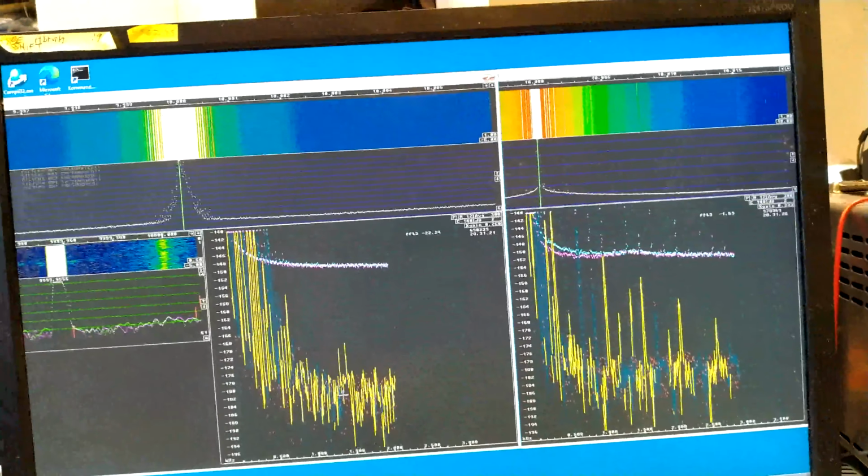And it's the same here. There are spurs, not very strong, but of the wrong sign, and here is a big one with the wrong sign. So the sound card is not useful for low sideband noise levels at frequency offsets in the order of a kilohertz or more.